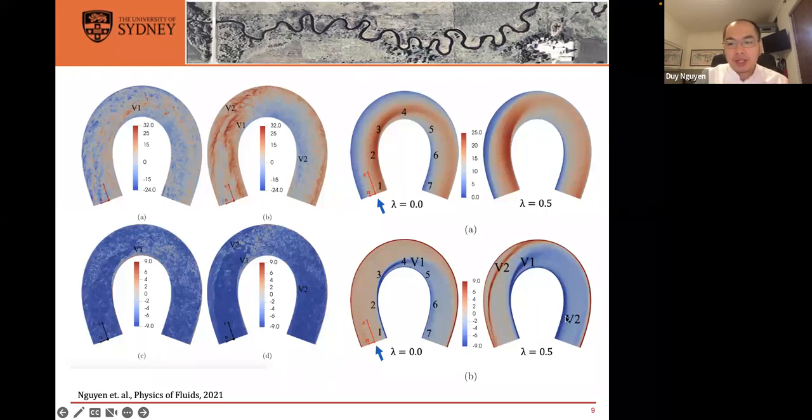So when we have another separate shear layer here, it actually goes out of the outlet and again gets picked up in the inlet by our anti-symmetric periodic boundary condition. Those two separate shear layers actually meet before the outlet here, and it amplifies the turbulence. So you can see that turbulent amplification is a well-known phenomenon for flow through a concave wall, but for